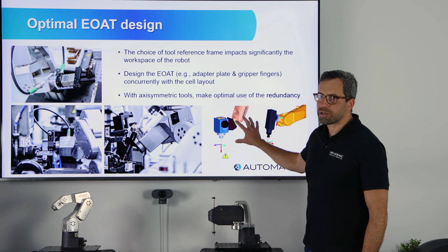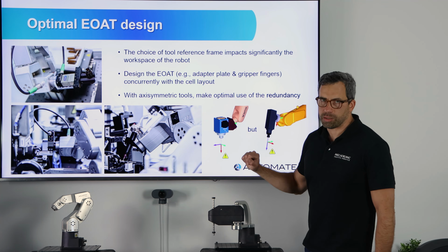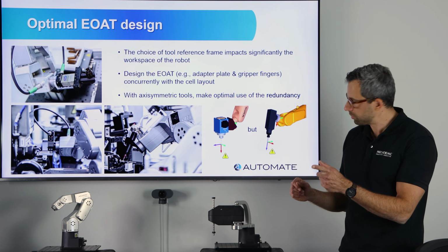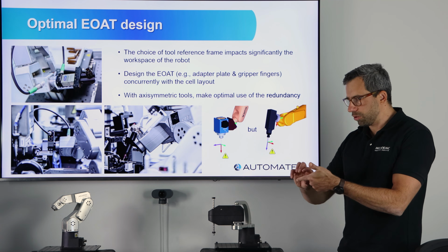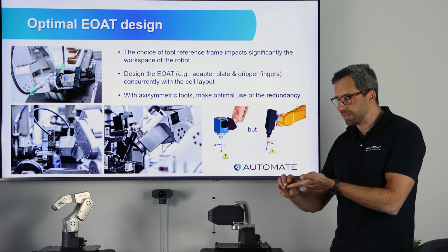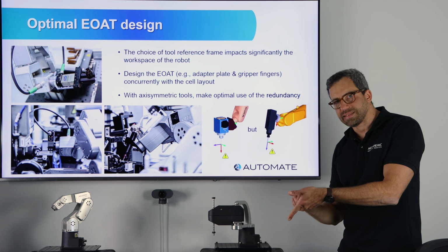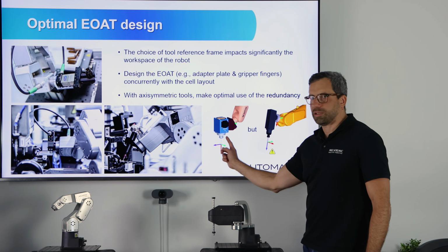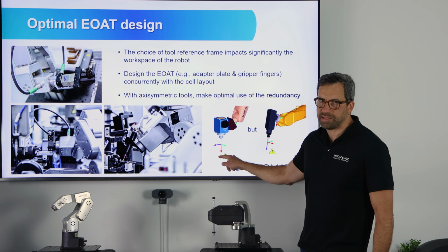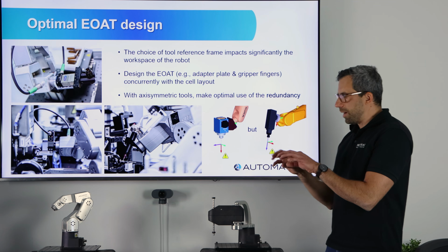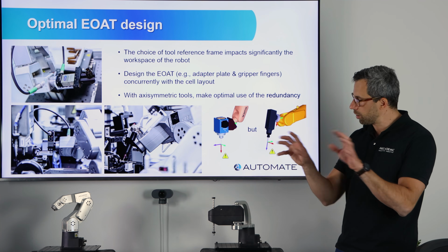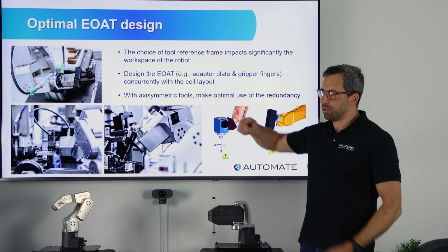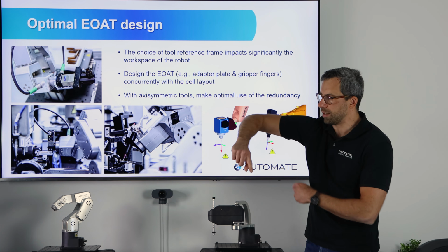If you have Kuka robots or ABB robots, for example, the Euler angle convention is rotation about the z-axis, followed by rotation about the y-axis, followed by rotation about the tool x-axis. So if you want to easily change the rotation about the tool axis, put the x-axis there, which is the final rotation. By changing only one Euler angle, not all three of them, you will be able to try different rotations. And by doing this, you can avoid singularities.